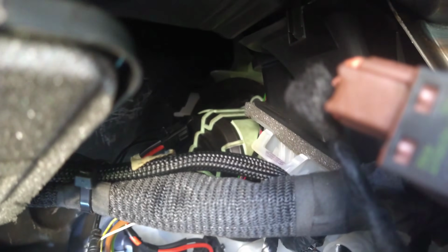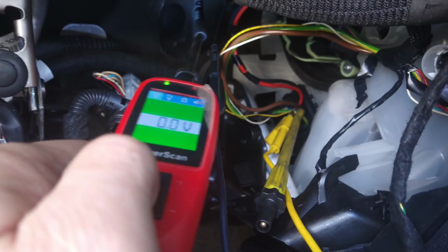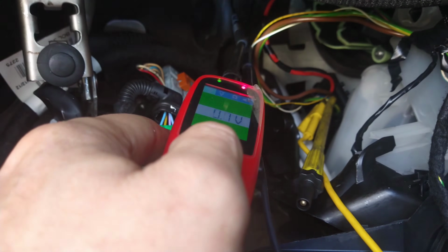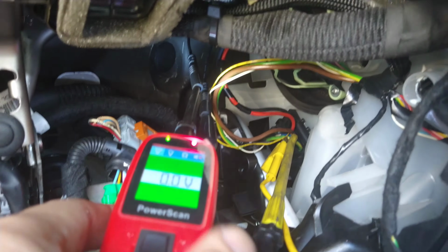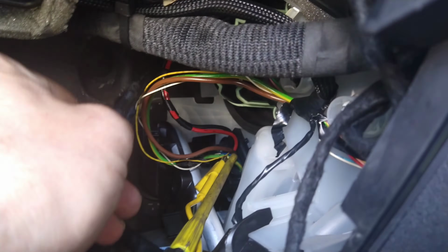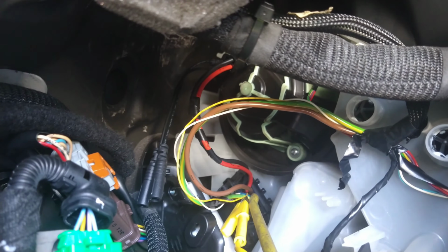But what I've noticed is I've just put two wires to go straight to the blower motor up there. And I'm using the power probe. I'll just get this on. Right. So it's green, so it means it's got continuity. But when I press this, I'm hearing a similar sound to what I heard. So I think the blower motor's got jammed up. I think something's got in there and jamming up the blower motor and stopping it rotating. So I'll need to take it out and see what it is.